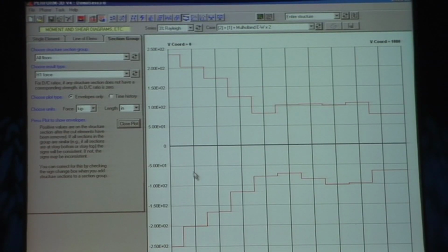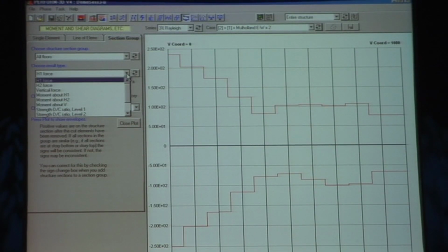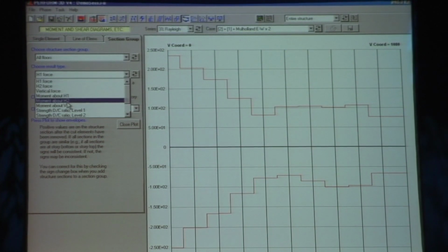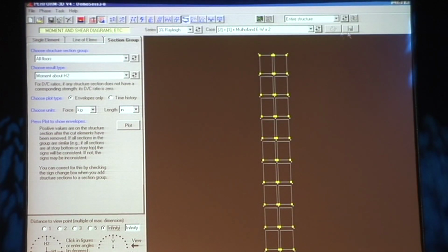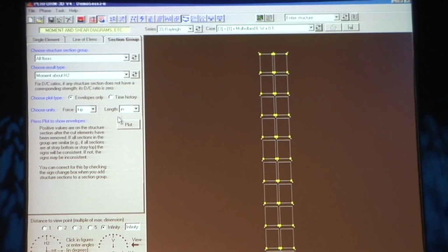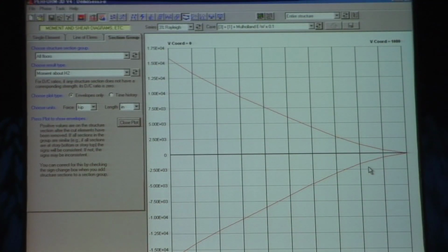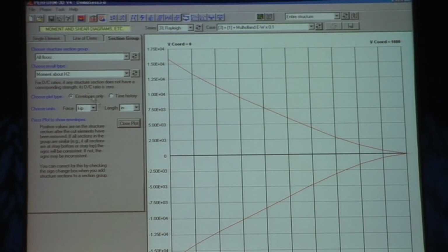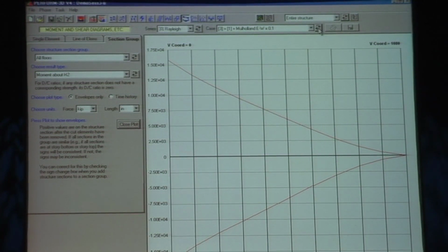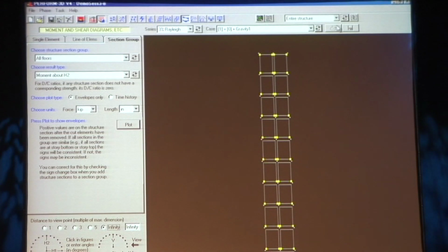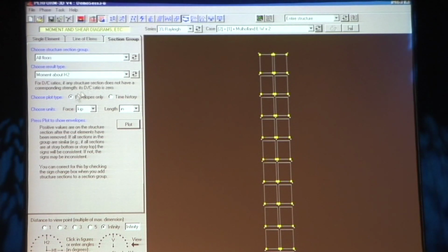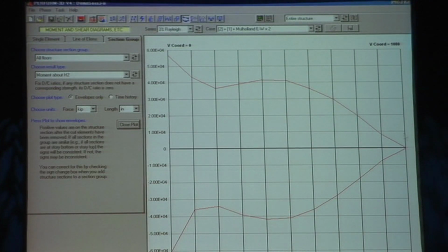And if we look at the bending moment, and again, if we look at the weak earthquake first, this is the moment envelope you would get from a linear analysis. Just look at the general shape, and then the moment envelope you get from a stronger earthquake: very different shape. Much larger moments higher up in the structure rather than the linear variation.